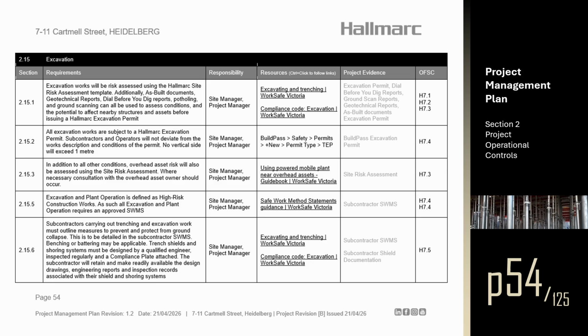Section 2.15. Excavation. Section 2.15.1. Excavation works will be risk assessed using the Hallmarc Site Risk Assessment template. Additionally, as-built documents, geotechnical reports, Dial Before You Dig reports, potholing, and ground scanning can all be used to assess conditions and the potential to affect nearby structures and assets before issuing a Hallmarc excavation permit.